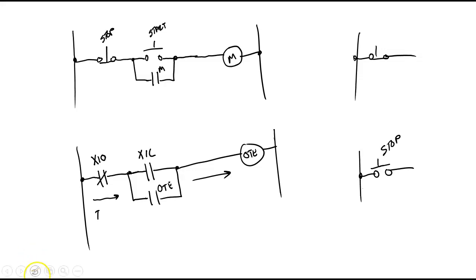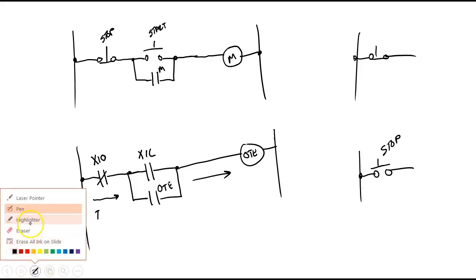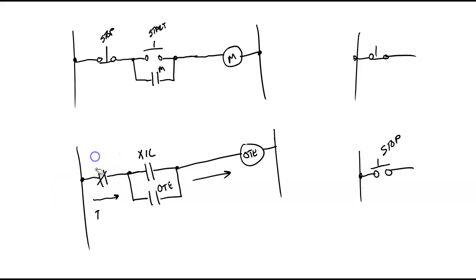So that means in my PLC for a stop button, I've got to use an examine if closed, because I'm using a switch that is normally closed, right? You understand? This makes sense now? So I have to use an examine if closed, because why? My push button is normally closed, and we say, okay, it's true if it's closed.